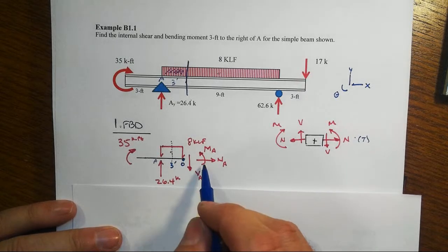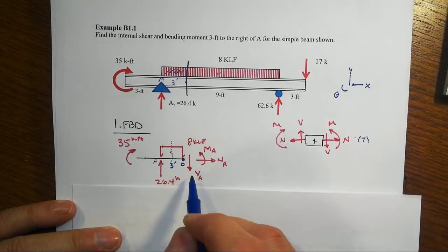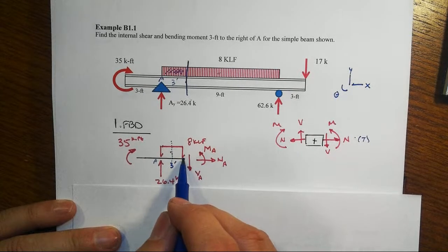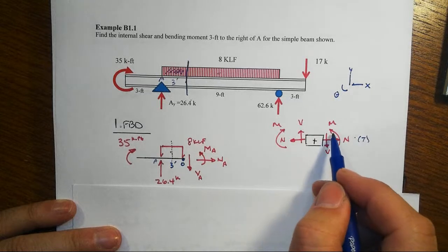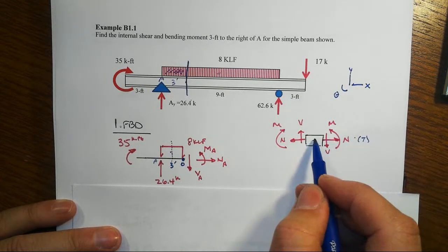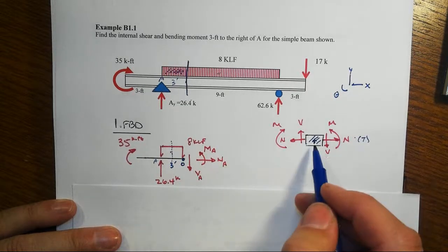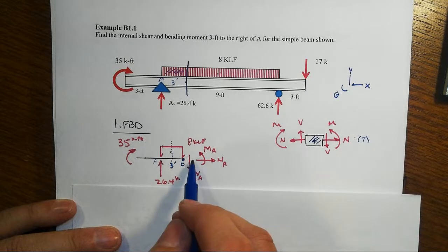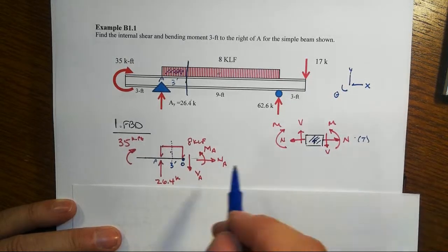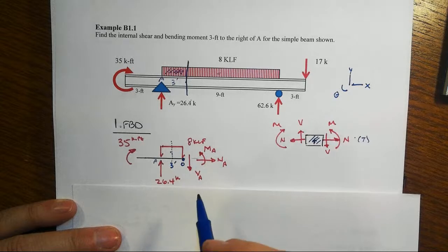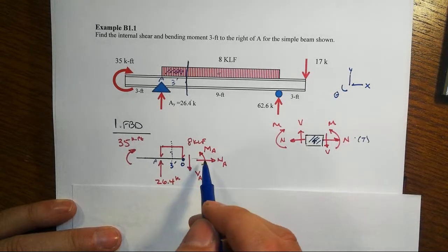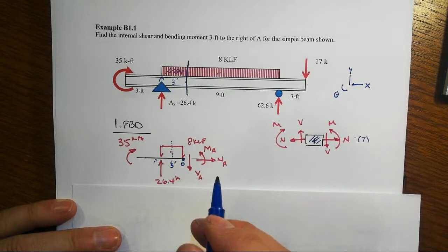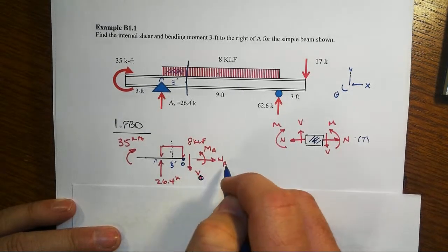Right? So that's why you see over here the shear at a point. I got V sub A going downwards. I've got M sub A showing, oh, this is the right hand exposed face, so it would be the counterclockwise one. How do I know it's right hand exposed face? Well, there's the solid, and the solid is to the left. The outward normal is to the right. That's the axial force, so we're on the right hand side. That's what makes that the M going in the positive counterclockwise fashion, M sub A, right? A because that's the point. Yay, that really shouldn't be A, that should be O.